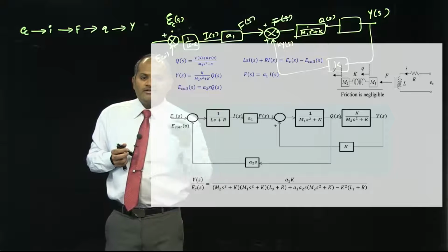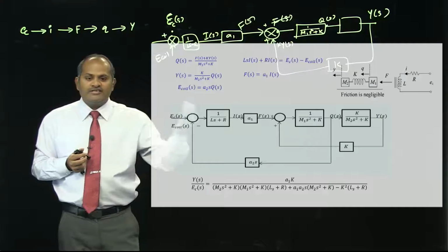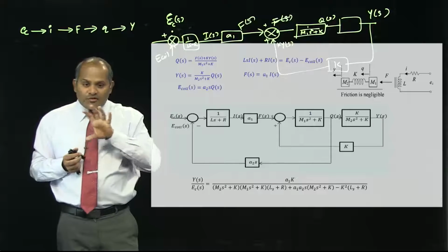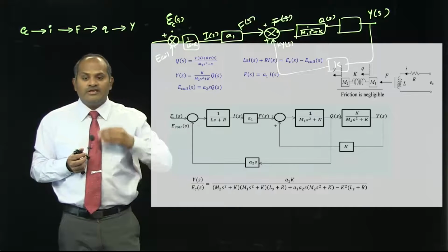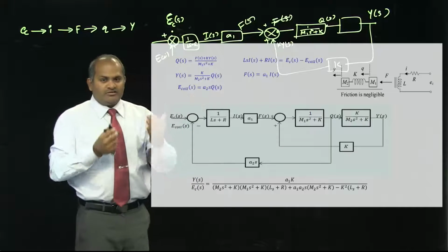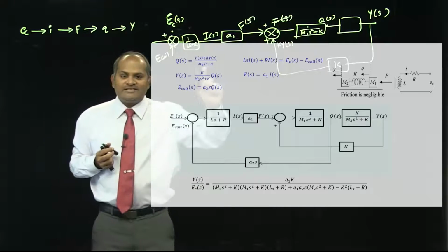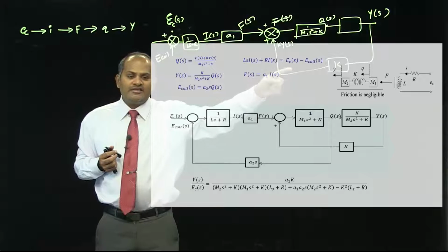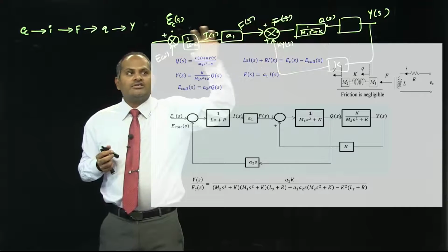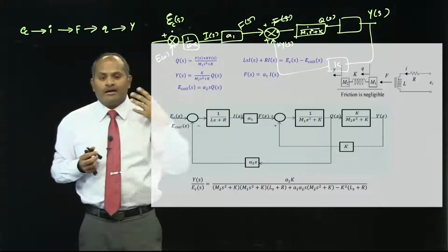The most important thing is how you start, stage by stage. Start at the output and work backwards. Never go from input to output, it can be very confusing. So go to the output and then work backwards. Whenever you see a plus and a minus in the equation, always understand that it is going to have a summing junction, and a plus or minus will be a comparator.